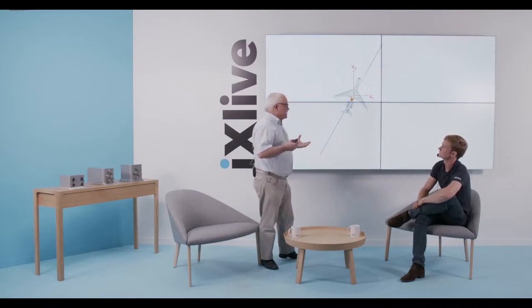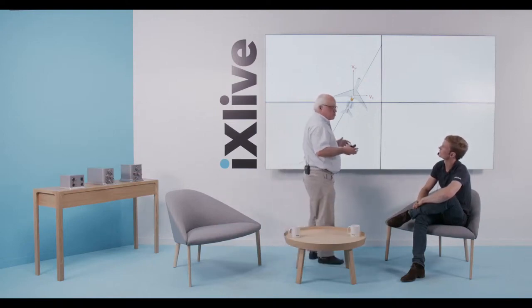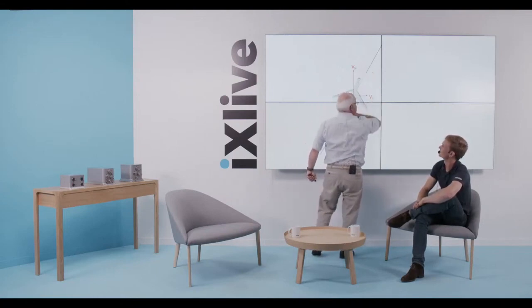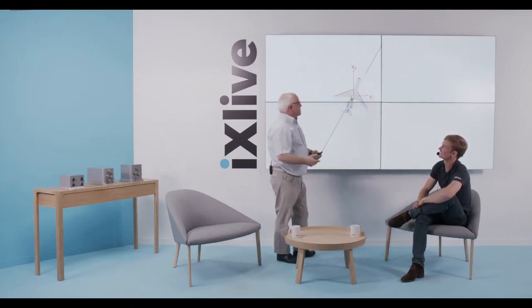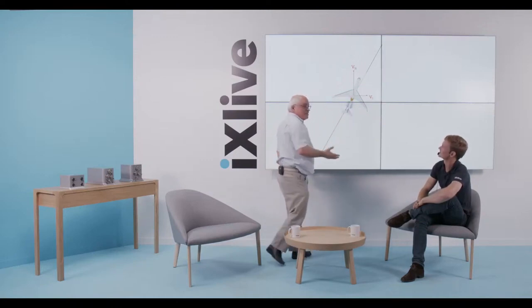And so it means that from the GNSS measurements, you cannot deduce what would be the heading. Imagine that there is so much wind, or imagine that the INS is on a crab. And so the crab could walk like this, and the difference between course and heading would be 90 degrees.